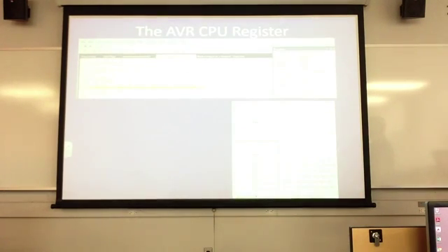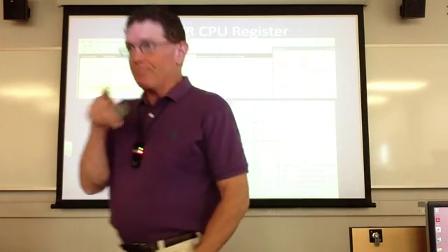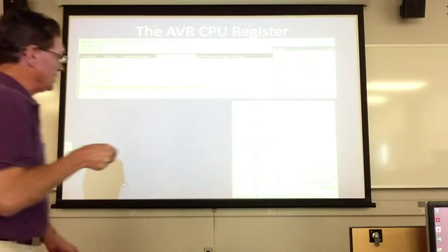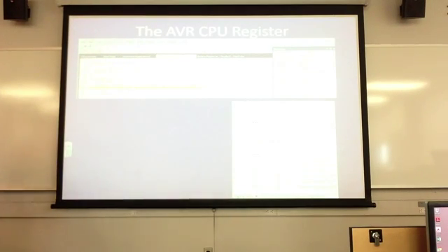All right, again, on your lab next week, we're going to be using the 2560, which allows me to do 16-bit addressing, okay? The question is, how do I generate a 16-bit address? Because if you notice, all of these registers and all this stuff is 8-bit registers. All the general purpose registers are 8-bit.